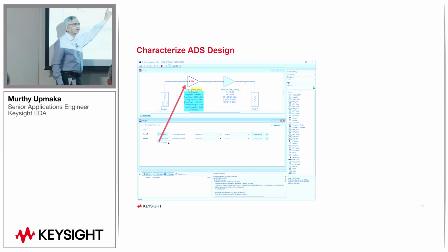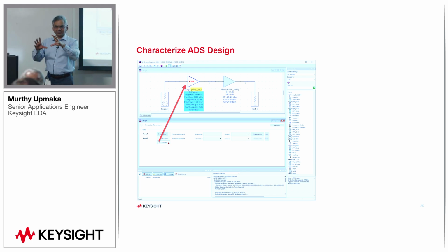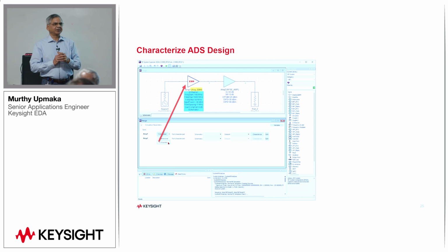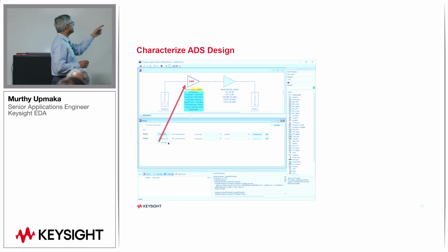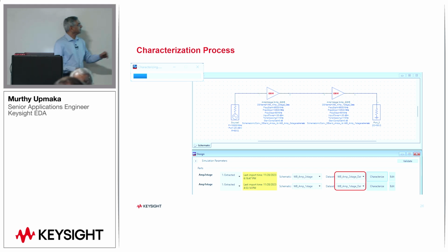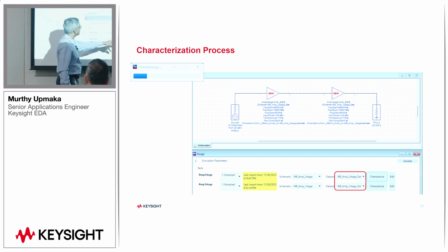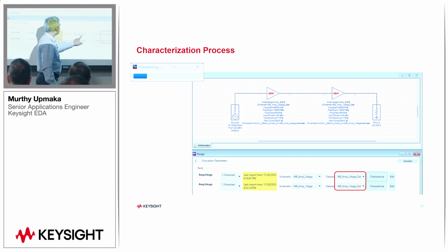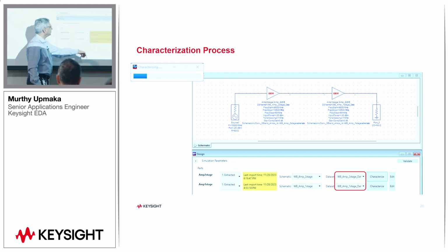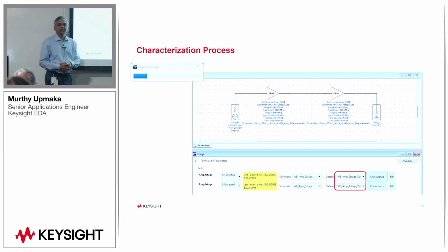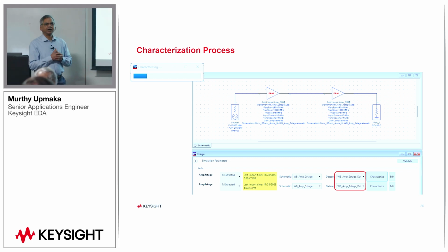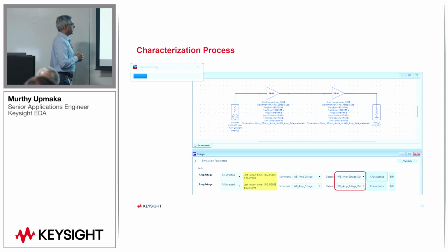After that, you're going to tell which schematic, your circuit schematic, you want to extract the behavior model from. So you're going to specify the schematic. Here both of them are selected as extracted, and the schematic is wideband amplifier 2-stage and wideband amplifier 1-stage. So there are two schematics that we designated as the candidates for extraction.